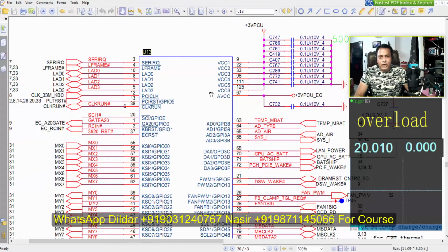There are a few things you have to check, like VCC must be available. I'm not telling you that it must be available or something you are going to check with the multimeter. Each and every point must be checked with the help of a DSO. Why? Because there may be some problem with glitches, the voltage is not stable, and there is a ripple. There might be lots of problems that could cause this type of light blinking. Every different case has a different scenario.